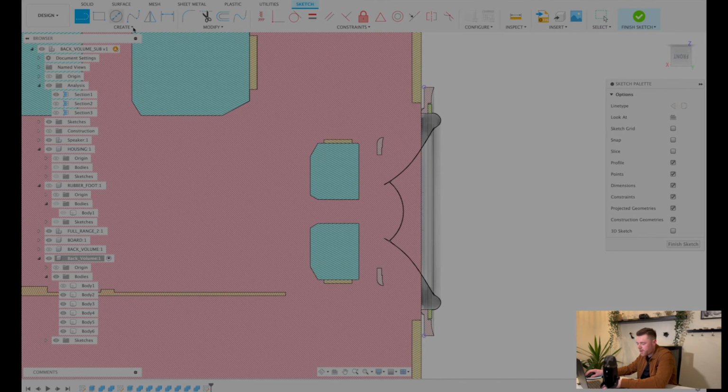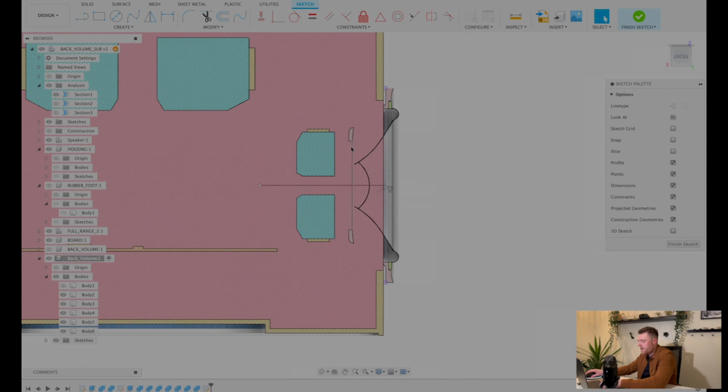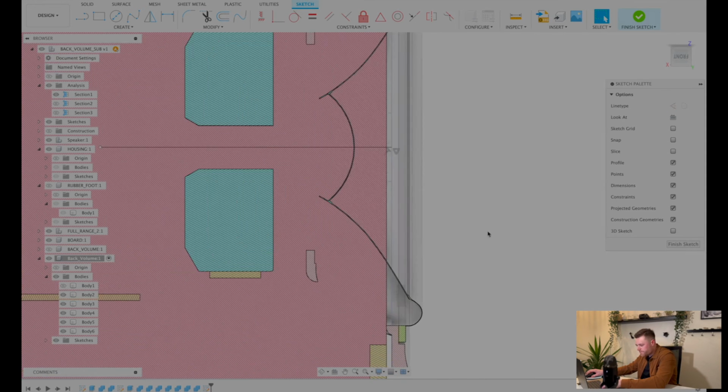And this is so we can create a center line at the midpoint of this axis. So if we just follow this all the way down until we see this center point triangle, and then make sure that we're at 0 degrees, we can use this as our center line, and then select and hit X to make it a construction.